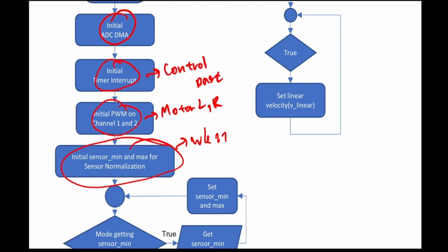If you measure the same color, it should return the same result, right? But in real life, it doesn't return like that. Some sensors, for the white color, should be 1000, but show 800 instead. That's why we normalize, changing from 800 to 1000 again.